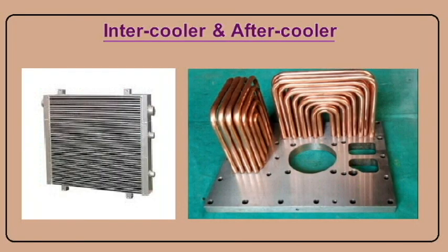Intercooler and aftercooler. Cooling medium can be air or water. Copper tubes are expanded in brass tube plates with allowance for expansion of the tube nest. Mostly water-cooled coolers are made with cast iron casing with a bursting disc, to protect against sudden overpressure. Drain pockets are fitted to remove moisture. Relief valve is to protect against overpressure on the air side. In case of tube leakage, the leaky tube is plugged or replaced.